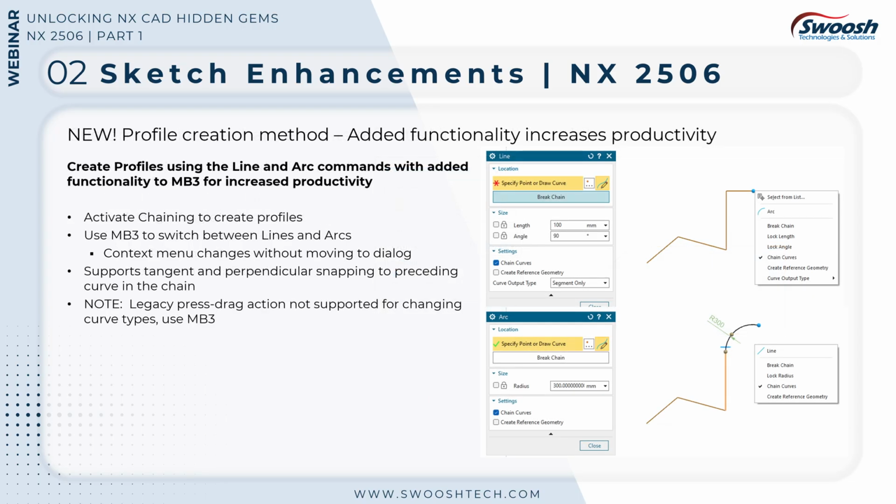A new profile function has been added and can be accessed via the right-click menu. When you begin drawing lines or arcs, you can enable the chain curve option either by toggling it on directly or by using the right-click menu to activate it. Once enabled, you can seamlessly switch between drawing lines and arcs using the right mouse button. The dialog box will automatically update to reflect the active function, and for example, when switching from a line to an arc, the interface will change accordingly.